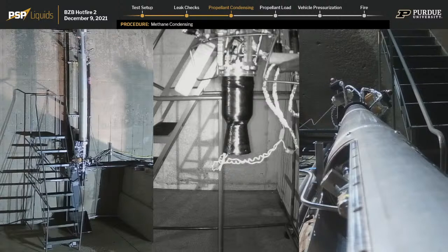As Carter is saying in chat, regen engines with a pressure-fed system would require very large tank pressures, and large tank pressures drive up wall thickness. Wall thickness would drive up total mass. And if you increase total mass, you need higher tank pressures. It's a really vicious cycle, and why we try to stay on the bottom of it this entire time.